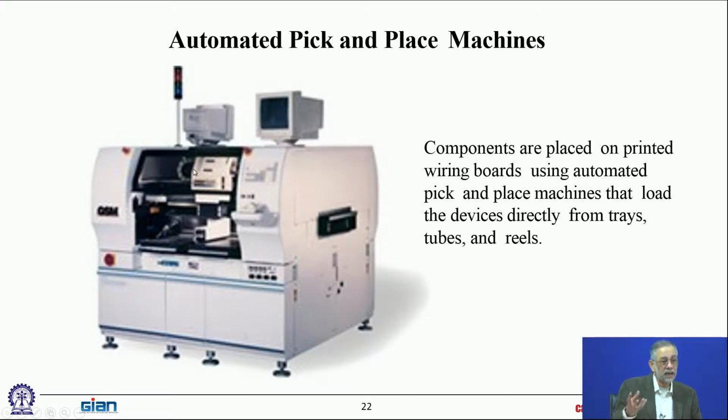These are basically pick and place machines. So these are highly automated in high volume production. These are machines that are computer controlled. So the circuit card goes and gets registered in the right location. It's all vision assisted registration and so on. And then this machine says, okay, I've got these 200 components that are going to go on it. That's already programmed in the memory.